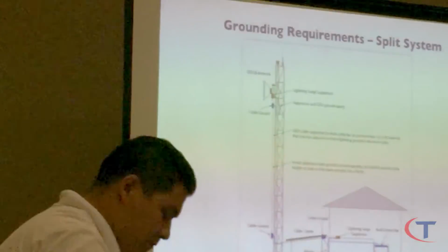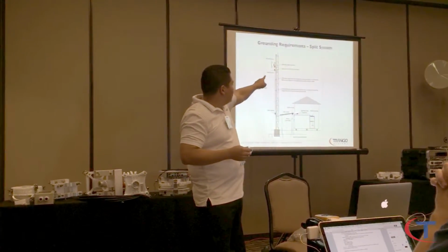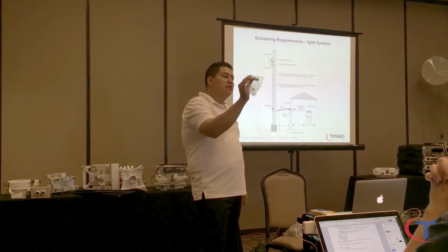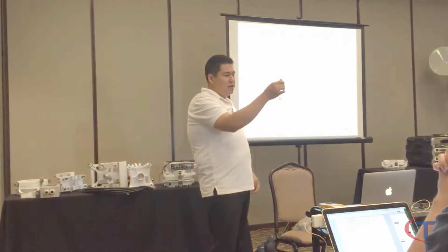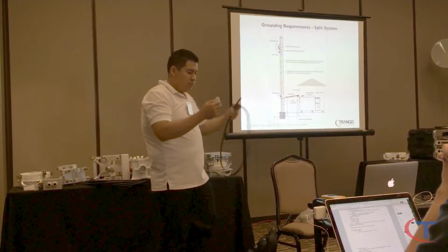Here we go. There are 2 types. We said a lightning surge protector goes straight on the ODU. This goes directly to the ODU. This is an inline polyphaser. So you put it in there, and then you take your LMR cable and stick it here.